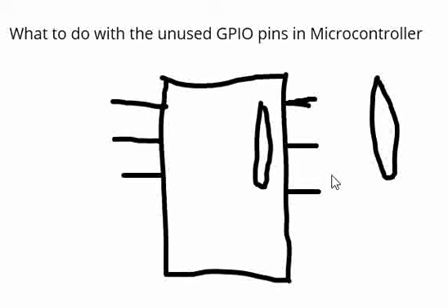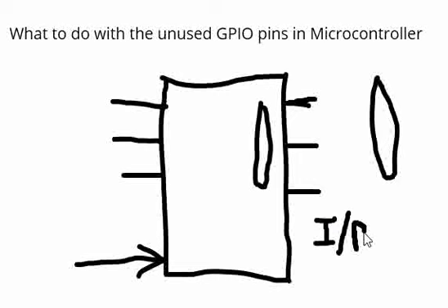So most of the time, when this particular IC is reset, if you take a microcontroller, these pins by default become input pins. So if you take any microcontroller, by default the pins will be in the input state. If you want to do an output operation on a pin, for example drive an LED, you will configure it as output and then use it.